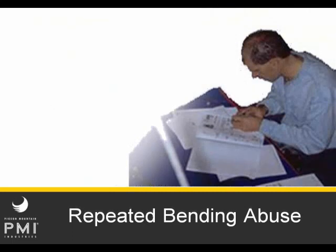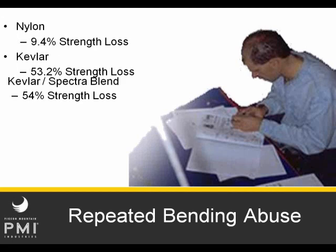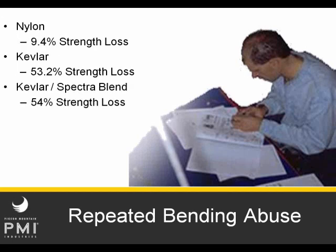What does this mean to the ropes that we use every day? Similar tests performed on other types of ropes had varying results depending on the fiber. As you can see, nylon is pretty resistant at about 9.4% strength loss under similar tests. Again, Kevlar was about 53% strength loss. Kevlar Spectra blend was about 54% strength loss. Spectra tested alone, just the Spectra, that test was pretty inconclusive, and that's due to the fact that Spectra is a very slippery fiber.